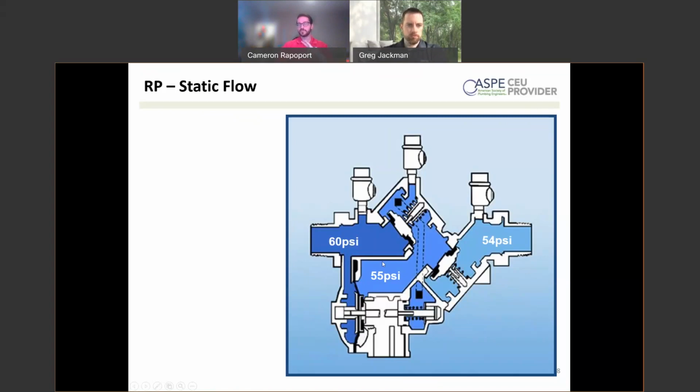You have the pressure between the 2 checks. This is the reduced pressure zone of the reduced pressure zone type backflow preventer. And you have a spring that is equivalent to 2 psi. So what that means is when this backflow preventer is healthy, that should always be closed because you should have a 5-pound differential plus, minus the 2 psi equivalent of the spring. You have 3 psi holding that shut.